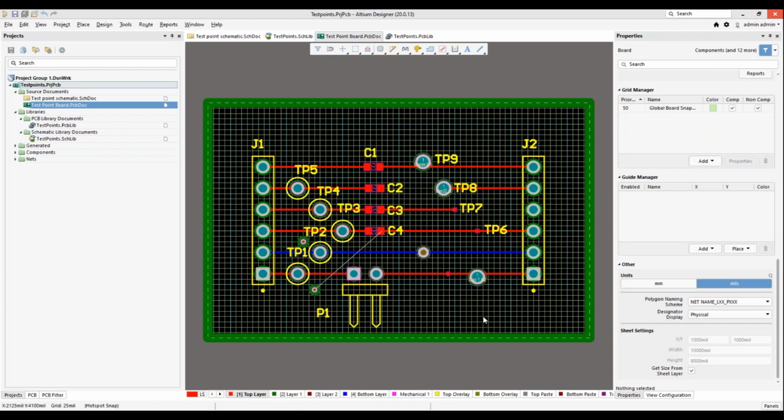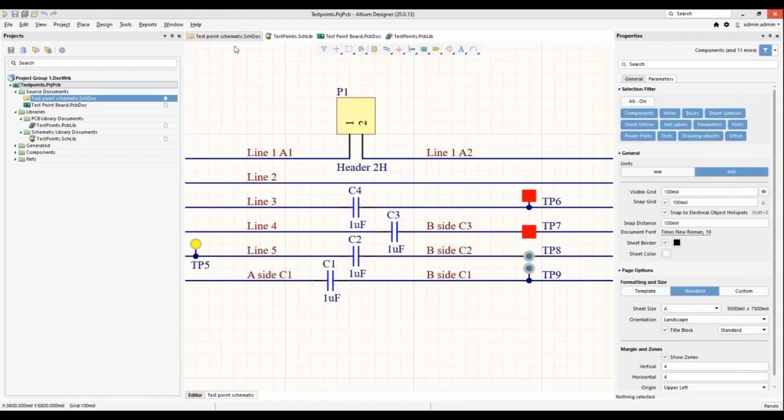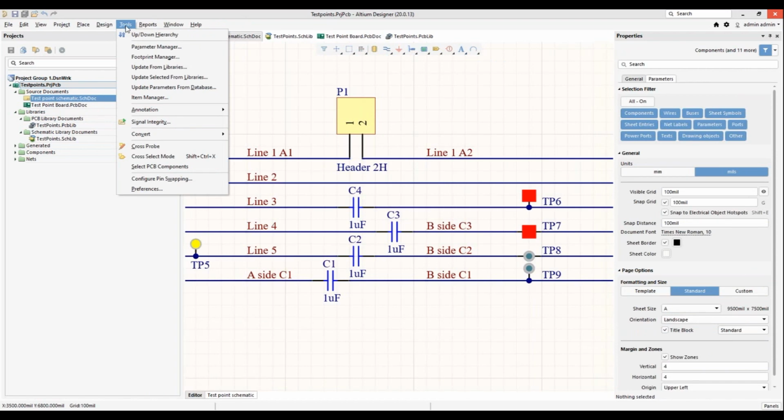To me, the Test Point Manager at times feels as though it is a fix for a library that should have had this to begin with. Very similar to the schematic documents, they have something called a Footprint Manager. And to me, there are times where you really do have to use the Footprint Manager, but it is very much a last resort. And if you're using it constantly, that usually indicates that your libraries are not up to par.